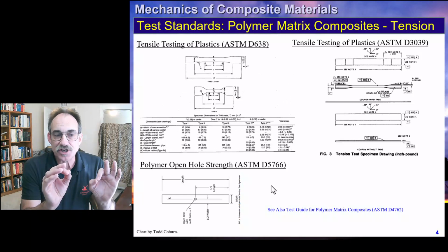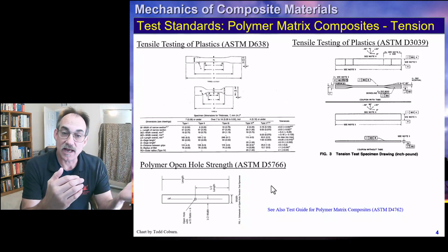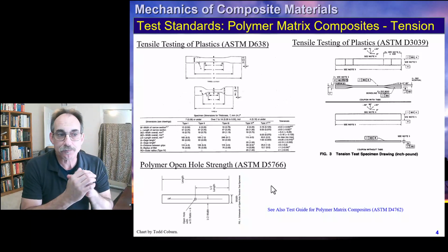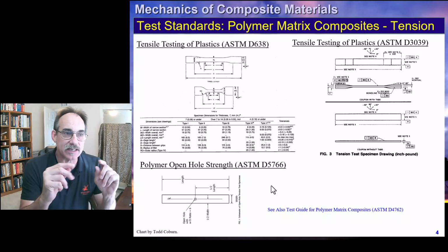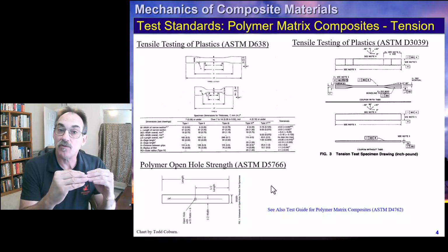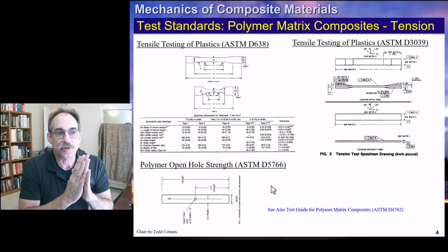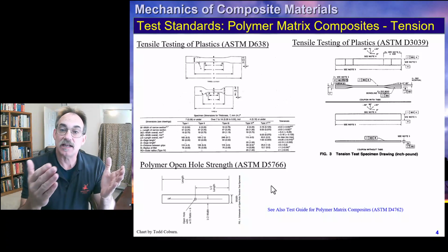But for much engineering work, especially as you get closer to the edge of what we understand, so you get out into more rockets and satellites, you tend to be working more on the fringes of knowledge. The important thing is to come up with a simple test that characterizes your material, that you can evaluate the critical failure modes, with a reasonable number of samples. 7 to 15 is a good number. 15 if you've got a little more budget.